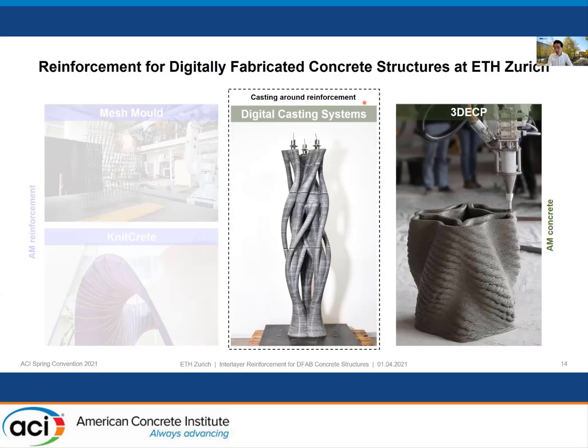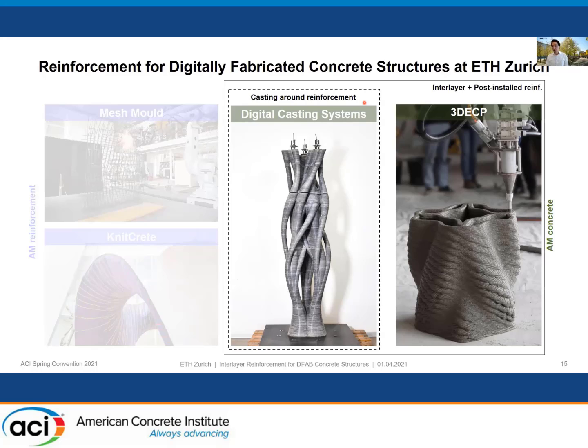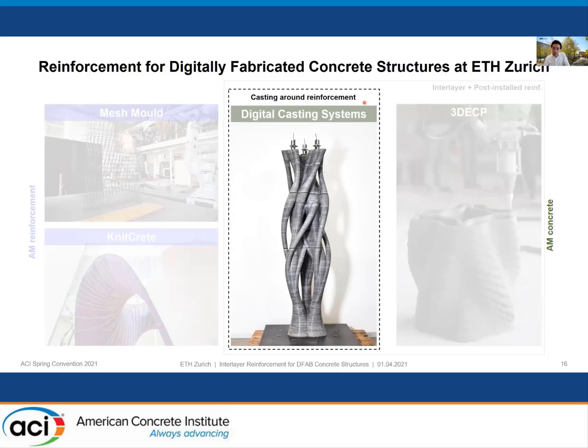But in some cases for digital casting systems, and in all cases for 3D concrete printing, we cannot place reinforcement sticking out. For this, we think that the concept of having an interlayer reinforcement after printing one layer, plus adding post-install reinforcement, is quite interesting. But before going to this topic, I would like to give a very brief introduction to these digital casting systems.